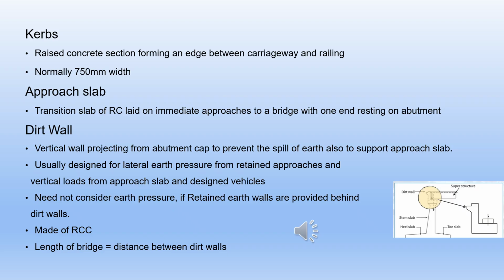They are placed usually on top of the parapets. Typically, they can reduce noise levels by 5 to 10 decibels. RC walls, polycarbonate panels, aluminum panels, etc., are usually adopted as noise barriers. Noise barriers are very relevant in the case of concrete wearing coat, where the pavement noise is higher.